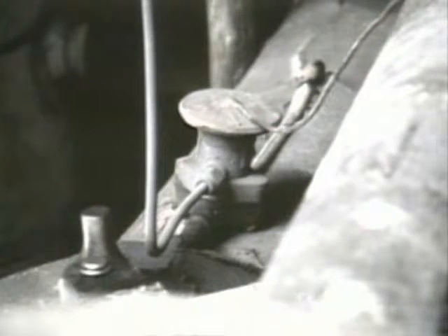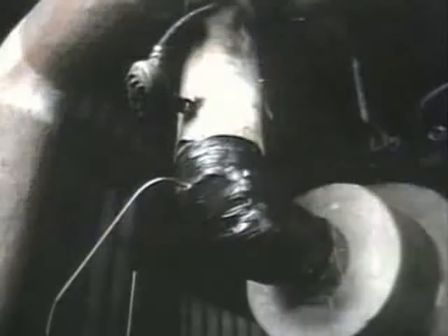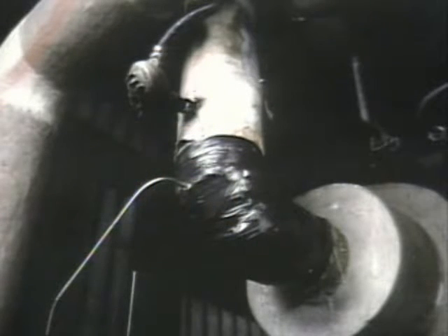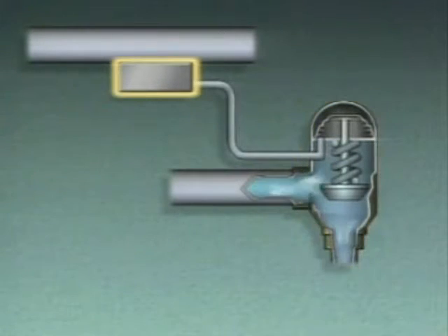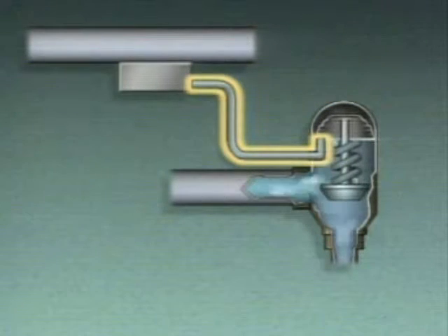The position of the expansion valve is controlled by the temperature of the substance being cooled. Some control systems use a thermostat located in the area being cooled to position the expansion valve. Other systems may use a thermal bulb or a thermocouple. We'll use an expansion valve and a thermal bulb to see one way to control the amount of cooling a refrigeration system provides. This illustration shows the expansion valve, the thermal bulb, and connecting tubing.